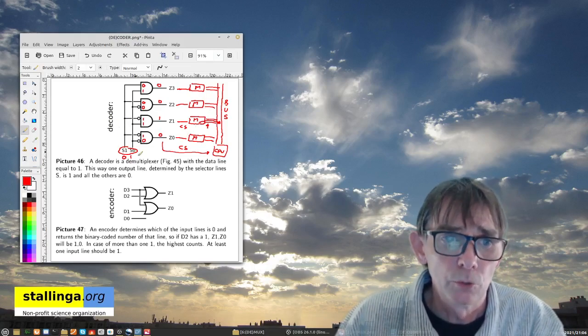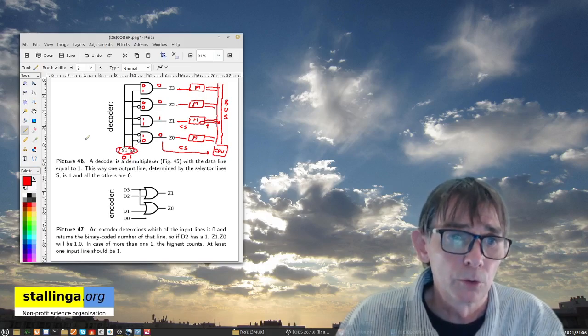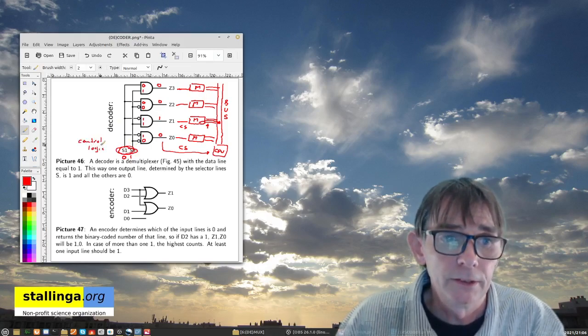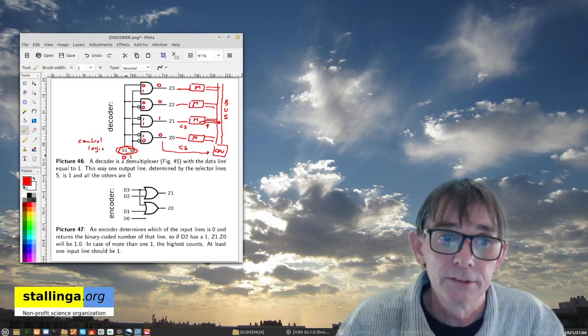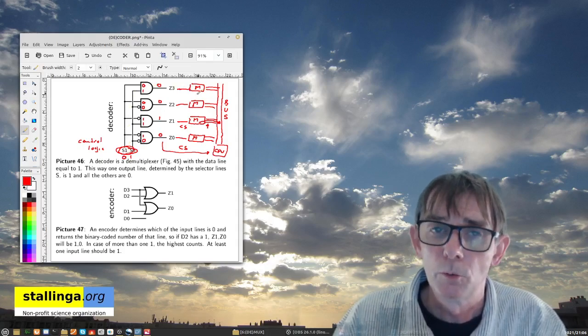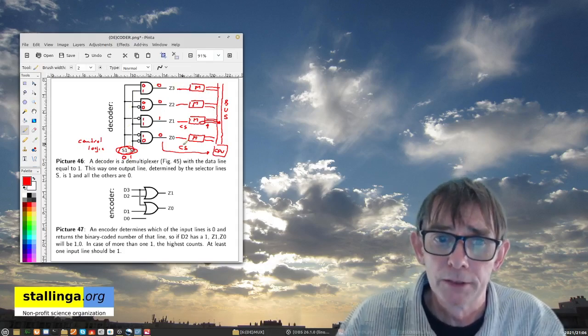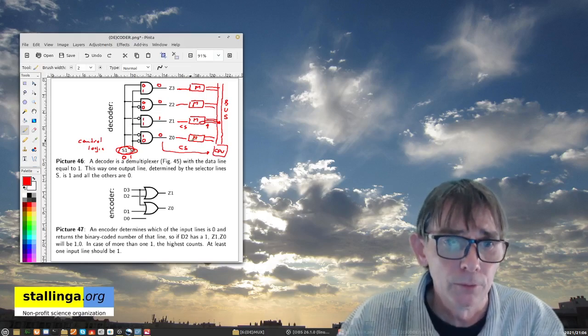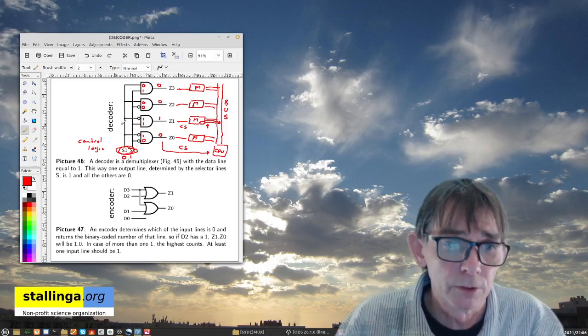You get the idea. So here you will have control logic that is then generating these selector lines, and these selector lines will make it so that only one component actually communicates to the bus and the others have to listen or be doing nothing at all. This is what we call a decoder.